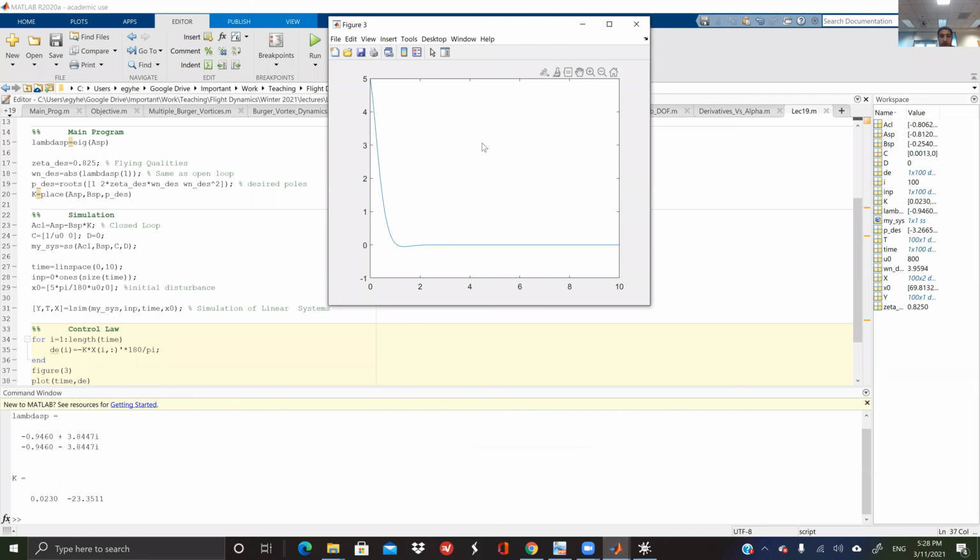Oh, here. Okay. Yeah, it actually follows. It starts with a large value because it was a large error. And then eventually, after you converge, it converged back. It shouldn't be the exact same value; like we give a 5-degree disturbance, you start with a 5-degree elevator. This is just a coincidence.